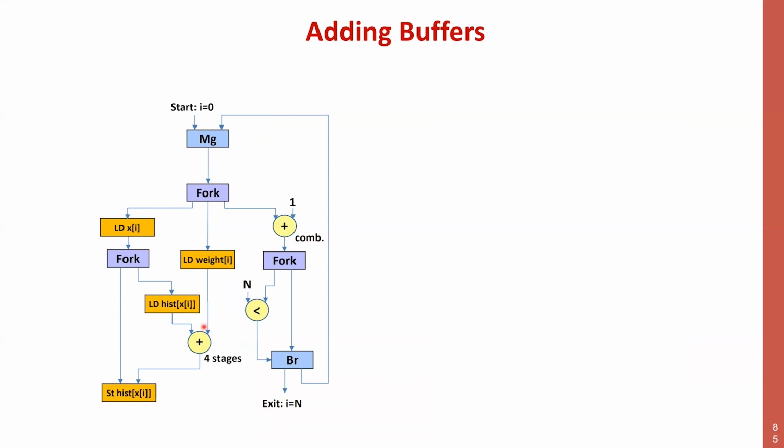So let's go back to our circuit that we have not yet studied very much, but we have achieved, and we thought it was a good idea. Now we have this problem that we have two combinational loops. Actually, they are mostly the same, but one passes here and one passes here on the left, and for the rest they are the same path. These two combinational loops should not be there, so I need to break them. And one possibility that makes a lot of sense is to break them there, right?